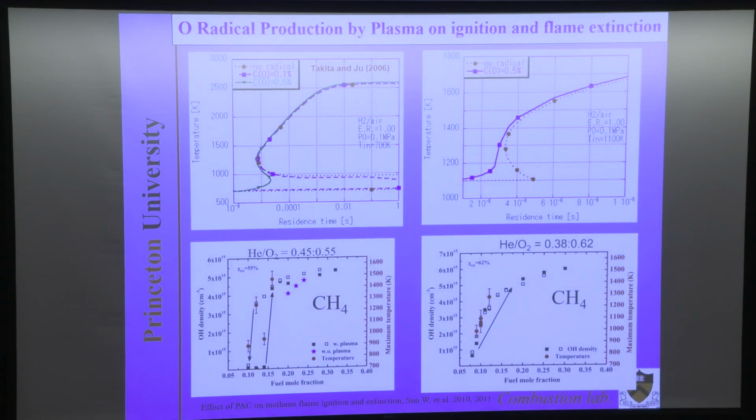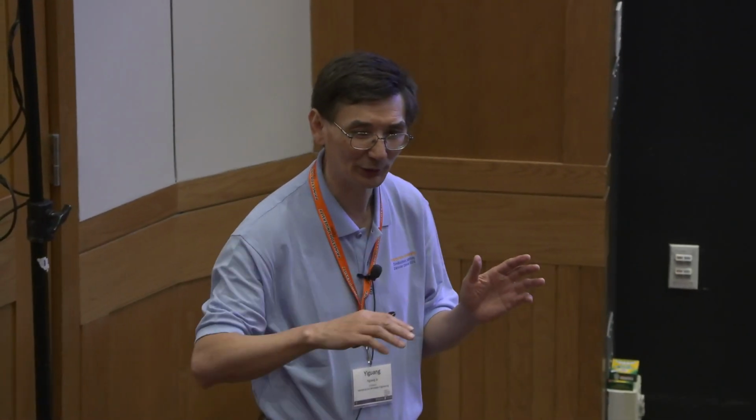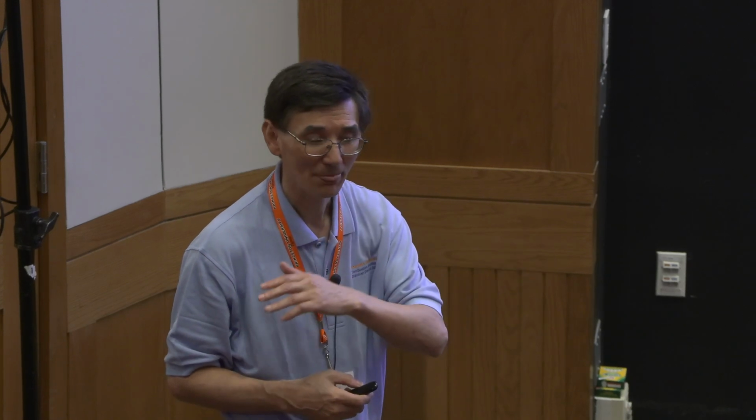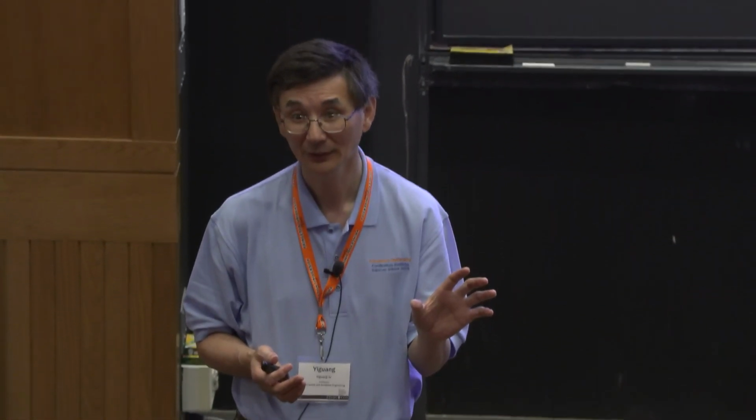So I think in the combustion field, there's flame stabilization in a gas turbine, right? You have a flame with much swirling. Most people believe that flame stabilization is because of the flame speed versus the flow: when the flow speed is larger than the flame speed, the flame blows off. But flame speed is very hard to increase, to be honest. Turbines can do it. But flame speed can be easily increased if the flame is an auto-ignition assisted flame. You see what I'm saying?